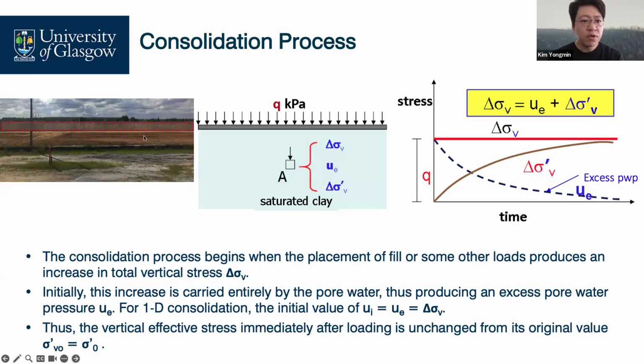When you apply your surcharge, which is the Q, your total stress is something like that. This load is supported by pore water, so your pore water pressure is here. But this pore water pressure is not hydrostatic pressure, it is the excess pore water pressure.